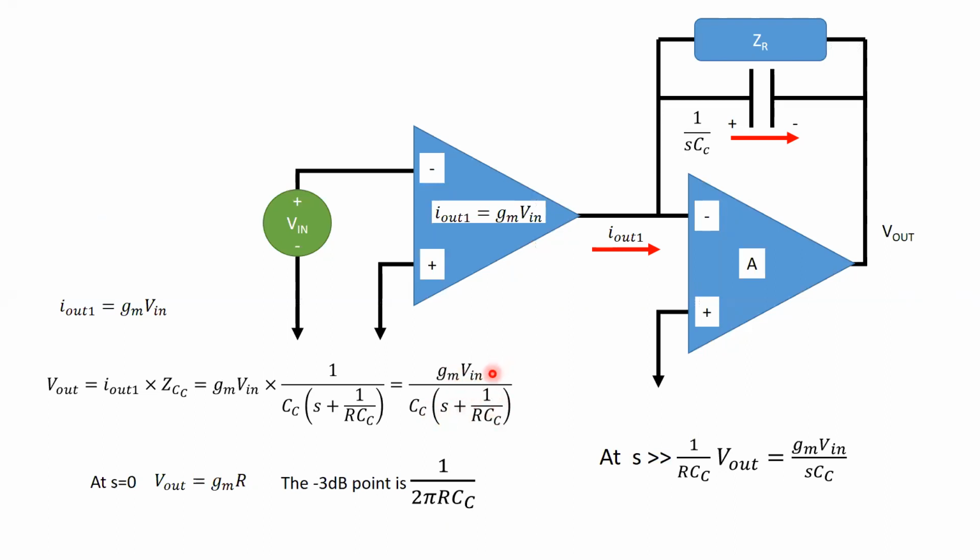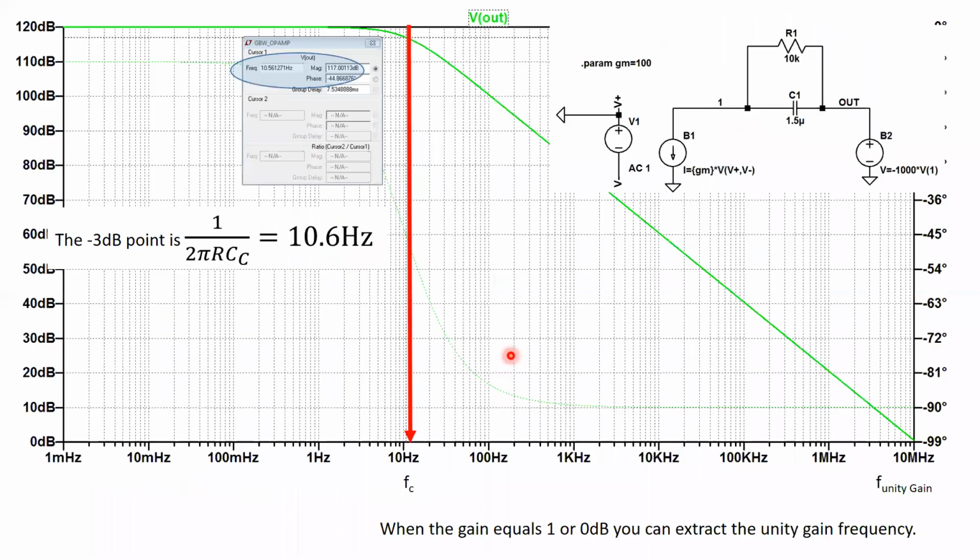All right. So in fact, in an ideal op-amp model, this line will keep going up towards infinity as we get closer and closer to 0. In a realistic op-amp, you get this low pass type of function. But remember, this is 120 dB, right? The gain is quite high. And then at 10 hertz, we're getting the gain is going down. And here's the thing.